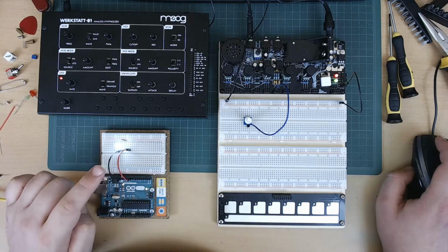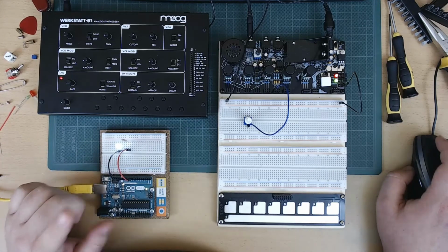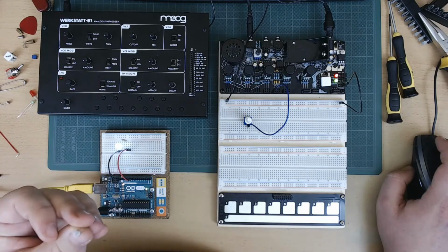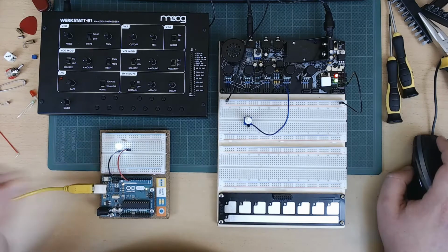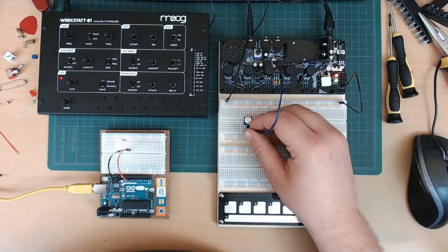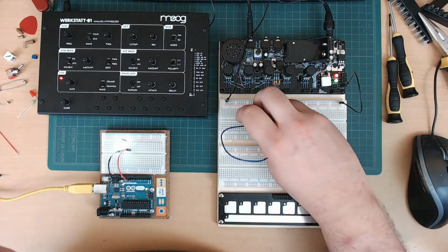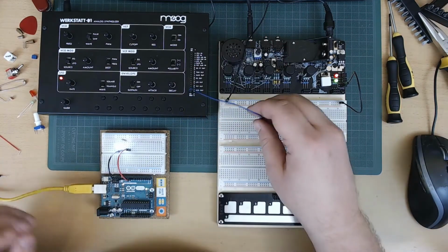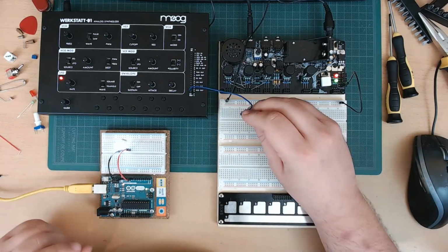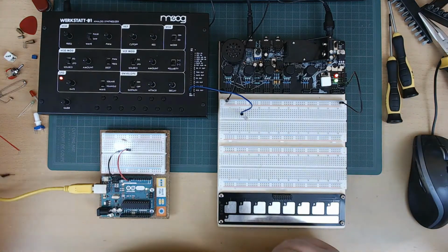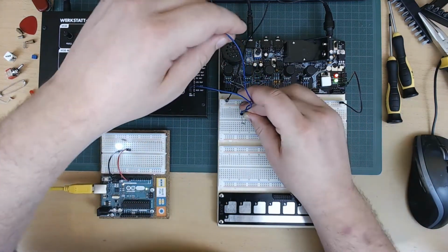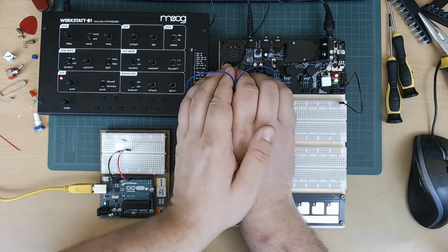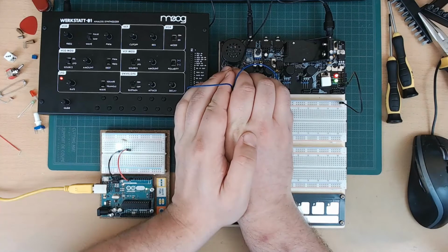there is a trick that has been used in synthesizers for quite a while called a vactrol. And a vactrol is basically a light-dependent resistor which you use together with an LED. So the principle is very simple. We go back to using a resistor on our audio. So from our oscillator through the light-dependent resistor to our audio out, we get our signal. And now if we make it dark around the resistor, the signal goes down.